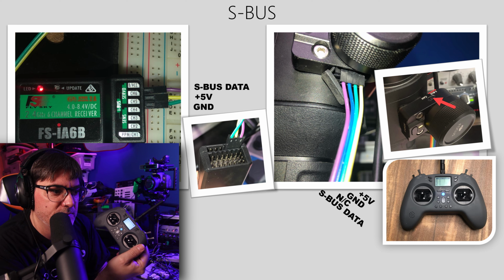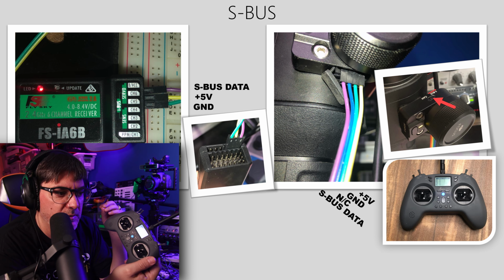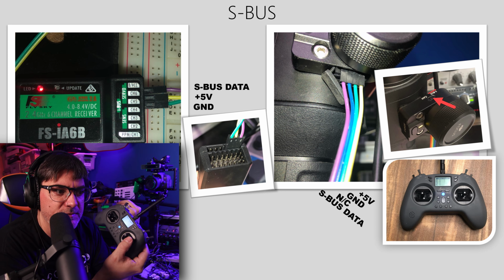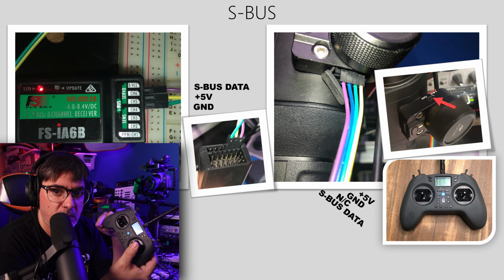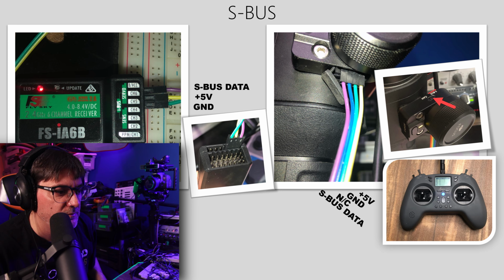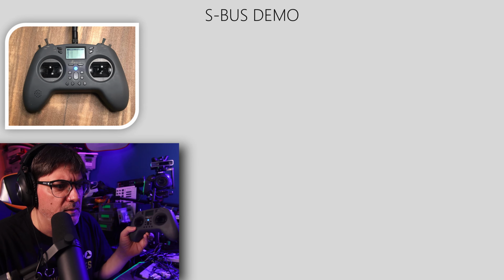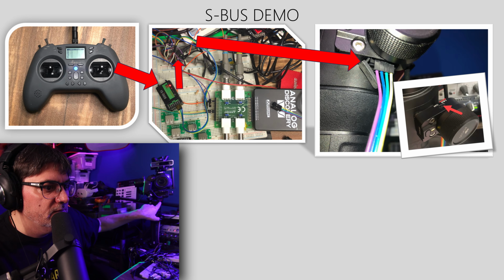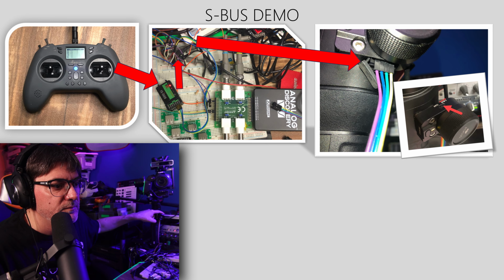The only reason we're going to use this is to sniff the communication and know exactly what's going on, and look at this information on the oscilloscope. So that's our next step, to connect all this stuff to the oscilloscope. I'm going to use this to send the information to the receiver. It's going to go through all this mess, and then the cable goes directly to the scope. You just have to make sure this is on the S bus.